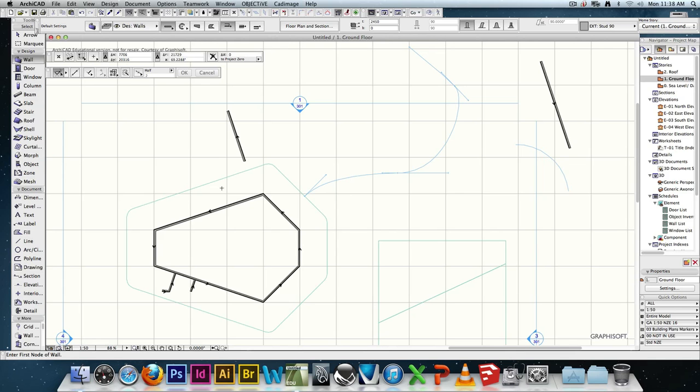But what happens if I wanted something that was 90 degrees to, let's say, this gap in here? Maybe I wanted to split this in half, but I want it 90 degrees to this imaginary line through here. Not a problem. Perpendicular to this. So this is now 90 degrees to this imaginary line through here. If I actually drew a line through there, you would see that that would be 90 degrees in there. So you either click on a line or define one.